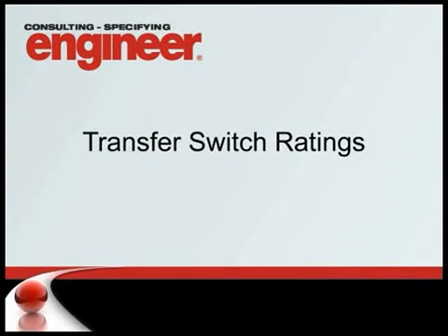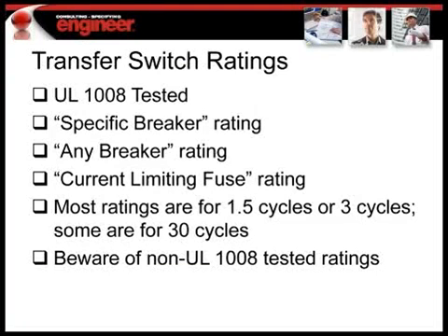So let's move on to transfer switches and how to apply them and how to choose them in a healthcare environment. Transfer switches are tested per UL 1008, and UL 1008 defines certain procedures for testing the switches. Many of the manufacturers publish withstand and close-in ratings for specific breakers, for any breakers, and for fuses.